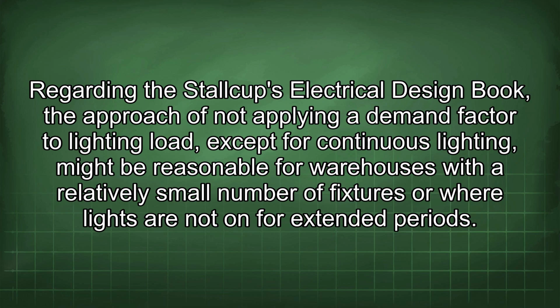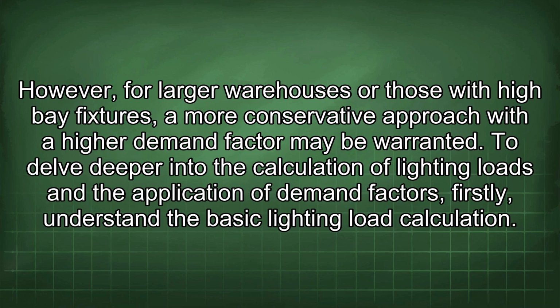Regarding Stallcup's electrical design book, the approach of not applying a demand factor to lighting load, except for continuous lighting, might be reasonable for warehouses with a relatively small number of fixtures or where lights are not on for extended periods. However, for larger warehouses or those with high bay fixtures, a more conservative approach with a high demand factor may be warranted.